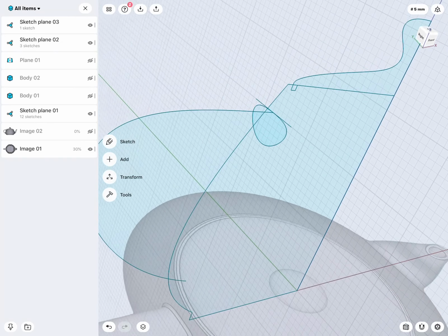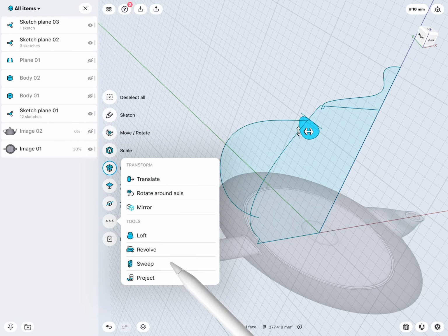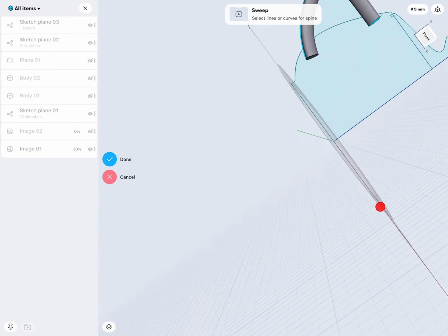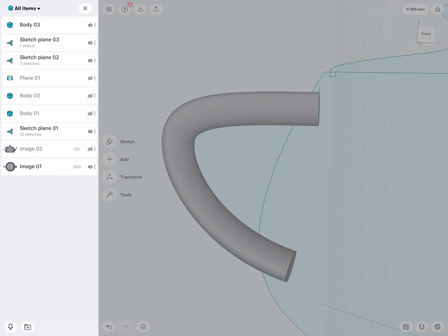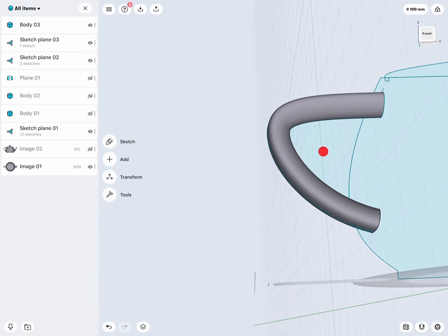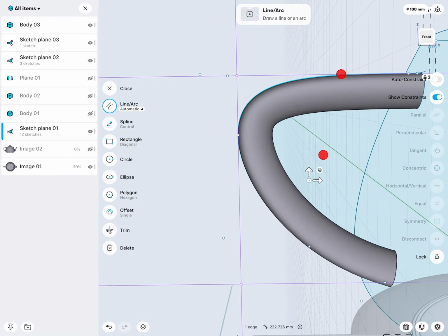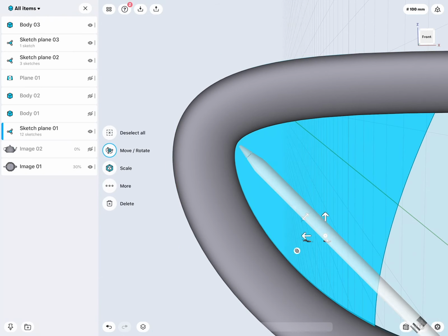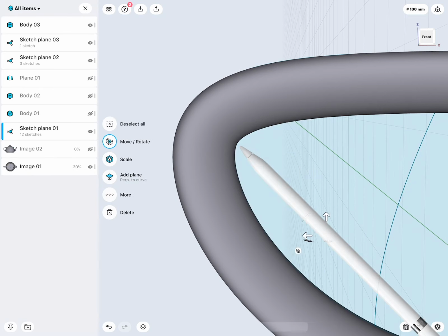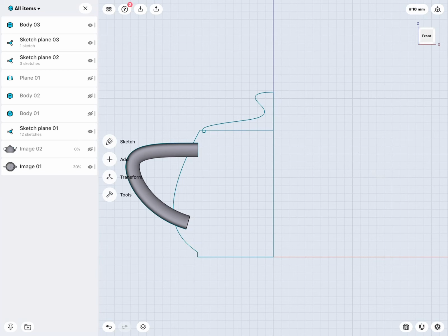So I lined this one up. Very good. So then this profile, I would like to sweep along this line. Oh, no, it's not a line, it's a curve. There we are. Cool. One thing to be aware of, this curve you can't make too tight because otherwise the sweep will start intersecting. If you take a look on the left outer curve, it's actually nice and round, and the inner curve where my pencil is just tapping, you see it can get actually pretty tight there. So just be careful about the type of profile you are creating.